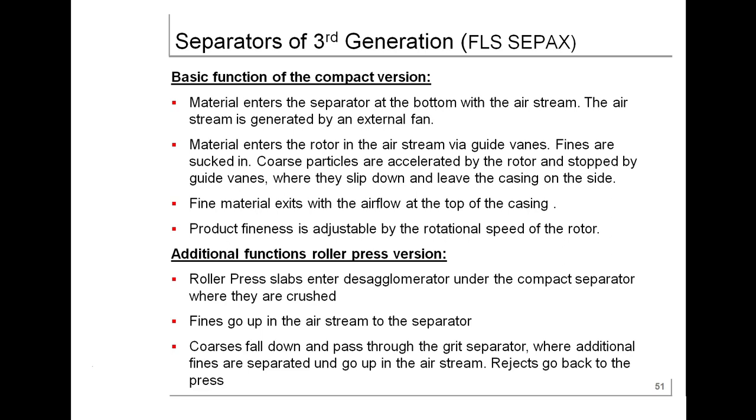Fines are stuck in. Coarse particles are accelerated by the rotor and stopped by guide vanes, where they slip down and leave the casing on the side. The fine material exits with the airflow at the top of the casing. The product fineness is adjustable by the rotation speed of the rotor.